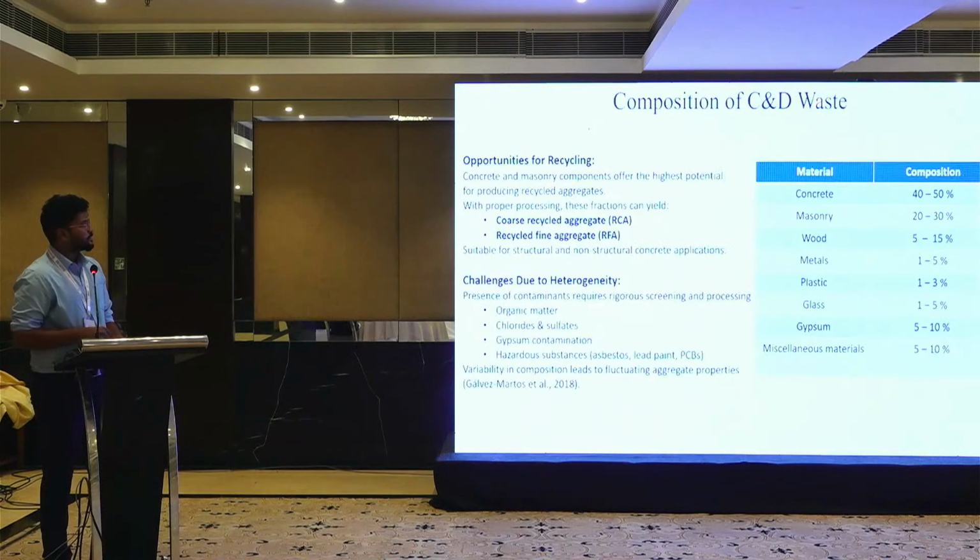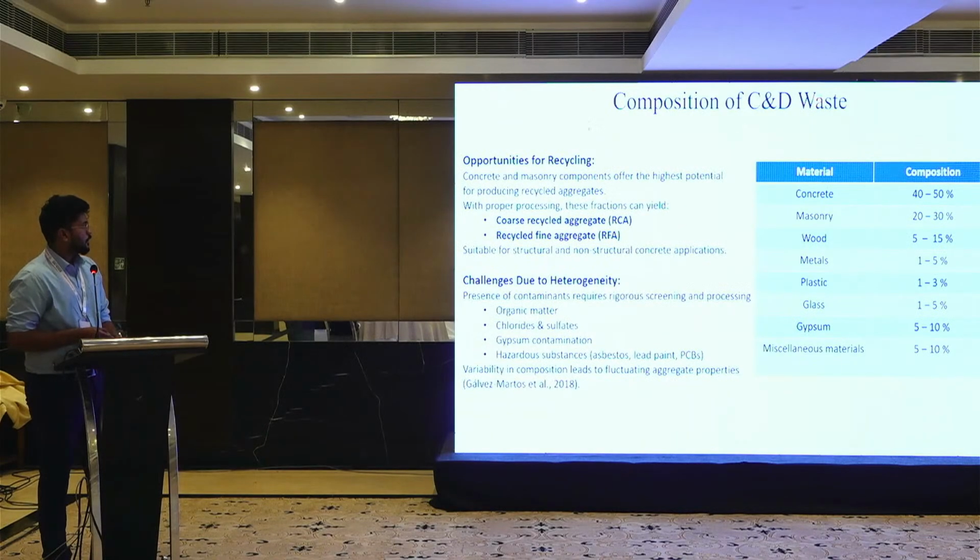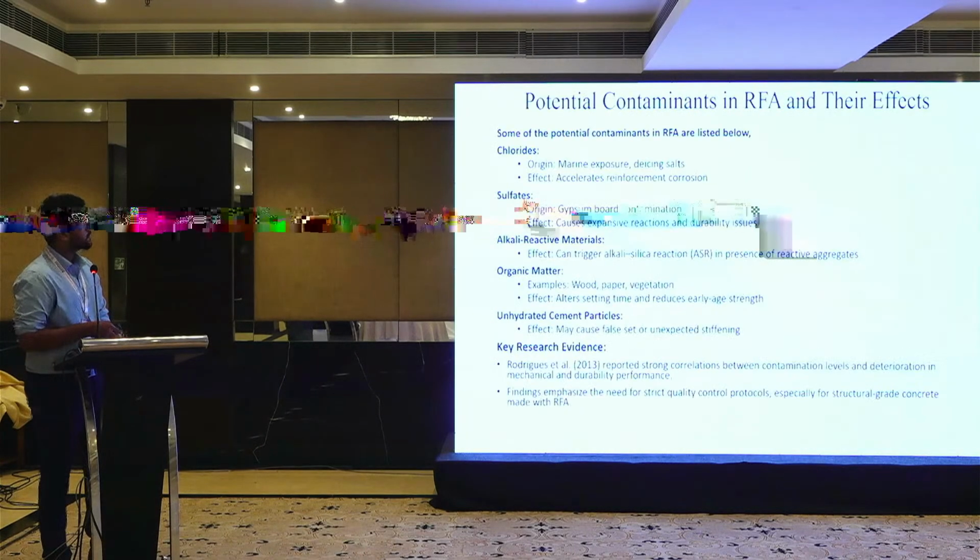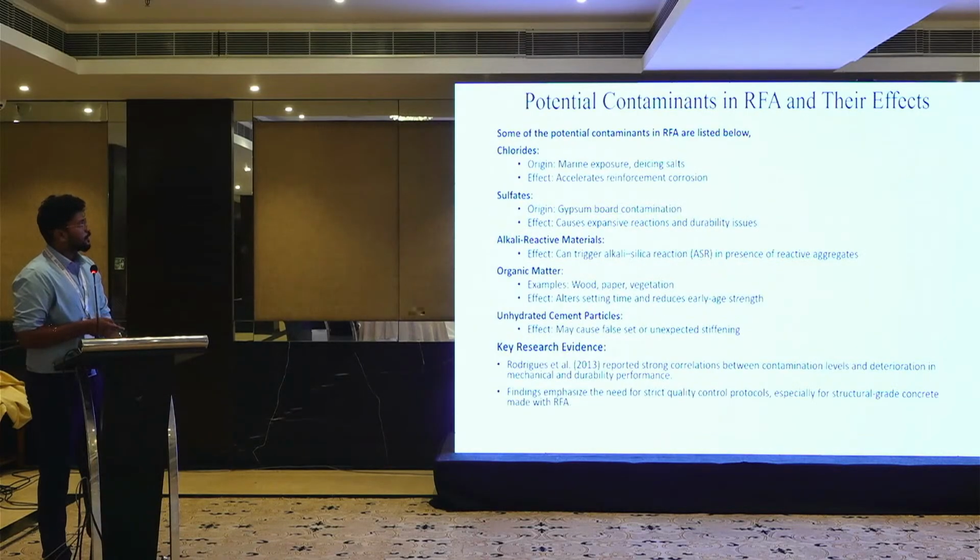Challenges and limitations. We can process coarse recycled aggregate and recycled fine aggregate also, and here we are taking up recycled fine aggregate. The challenges are organic matter, chlorides and sulfates, gypsum, and hazardous materials in C&D waste. These present potential contaminants in RFA, and we look at their effects.